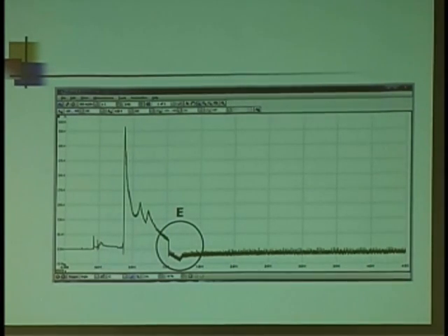Okay, we got the car running. Notice now how we've got current going in the positive direction. This is the draw. This is going back into the battery. Remember how that little short slope on the voltage screen went up to charging voltage? Well, that's the current that brought it there. Do you think if I measured that peak level, I would have a good idea of alternator output? Sure. And again, I'm not doing anything to the alternator to hurt it to find out.